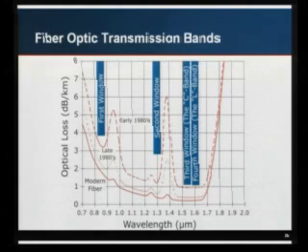So here's a diagram that I saw from someone somewhere that shows the progression of fiber technology. You can see in the early 80s fiber, there were very clear reasons why you had to pick certain frequency ranges. There's a limitation called water peak. What happens when they manufacture the fiber is, I'd probably talk about that somewhere else. I got my slides swapped around, but there's a manufacturing process problem where you get hydroxyls in the glass that you can't get out, and the water absorbs specific frequencies of light.